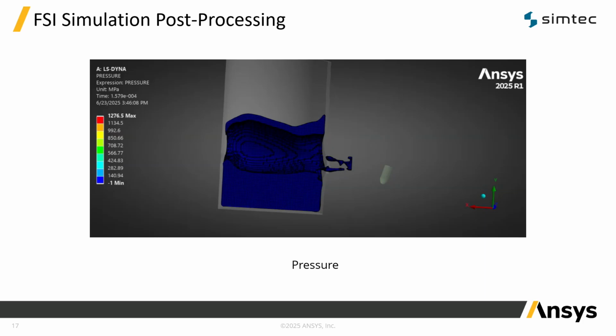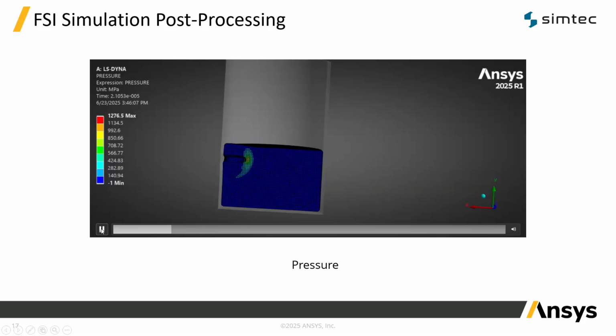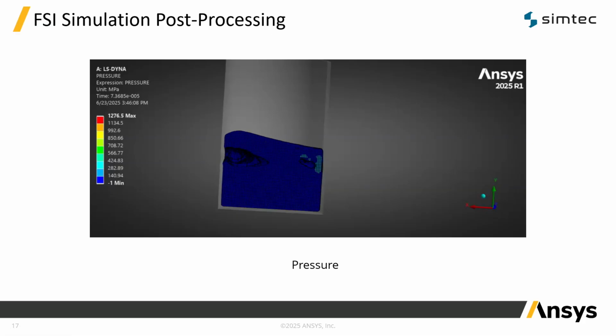This type of output is extremely valuable in design. It tells us where sealing might fail, where valves might deform, or where we need reinforcements. It's also a great diagnostic tool. If unexpected pressure spikes appear, it might indicate a modeling error, sharp geometry, or instability.